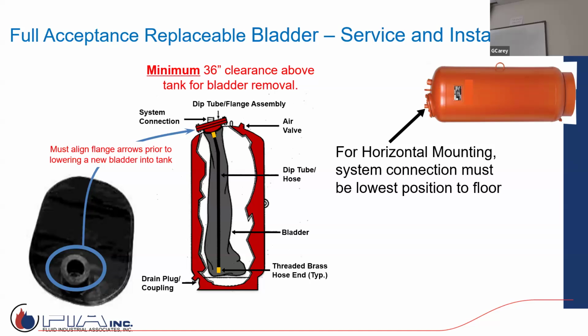Before the system turns on, you've got to remember that whole system's filled with water. There are no gaps. Water is not compressible. You heat it, it's going to expand. And either pressure is going to take off like a rock, or you have a place for it to go, squeezing against the air. The tank is sized such that as that air is getting squeezed, pressure is rising, but we sized it so that the relief valve never even saw that increase to the point where it opened.